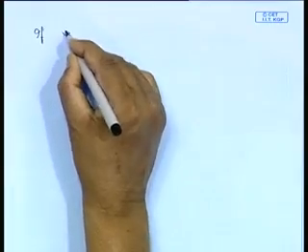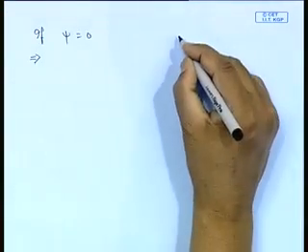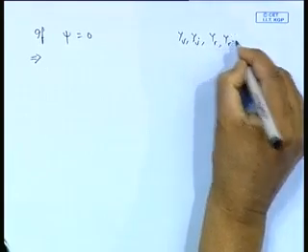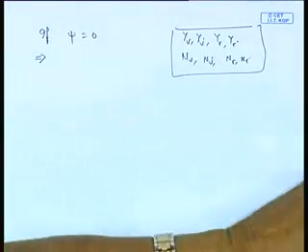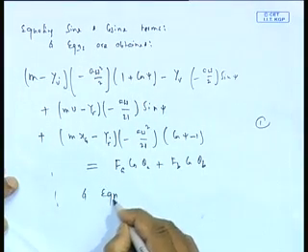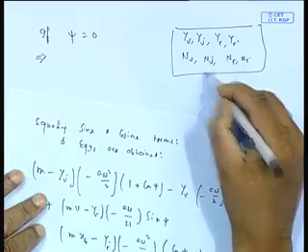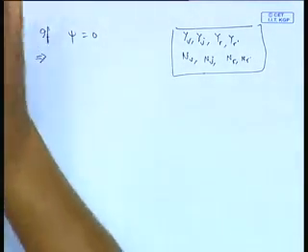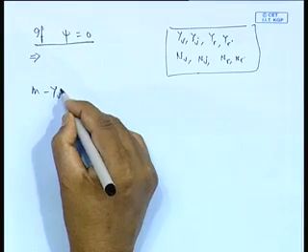The interesting point is that after you get these 4 equations, I will not go through them, but you do them, then you will see that if you put psi equal to 0, remarkably, actually here you are going to get 4 equations with unknowns y v dot, y r dot, n v dot, n r dot. You will end up getting 4 equations with 8 unknowns. Those are these 8 unknowns. But now the most interesting part comes out. This I will leave to you as an exercise. Now you make psi equal to 0, you will end up getting 4 reduced equations with only these 4 unknowns. For example, I will just give you one example, y v dot.